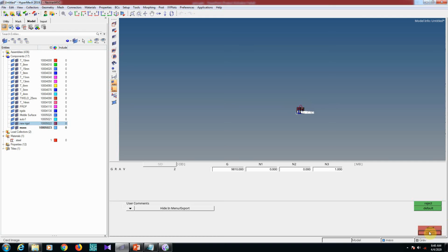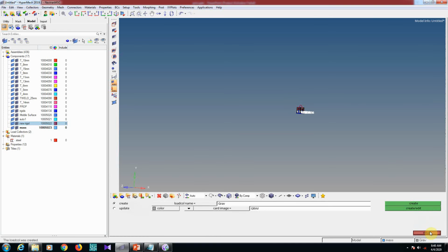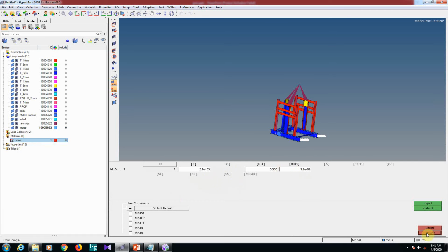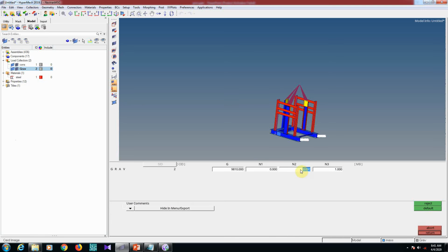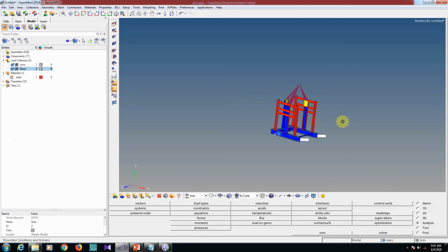Actually, if I use the Z direction, the structure orientation is in the Y direction, so I can't use the Z direction. Instead of that, I can go ahead with the Y direction, make Z as 0. Then come back, then we need to define the load step.